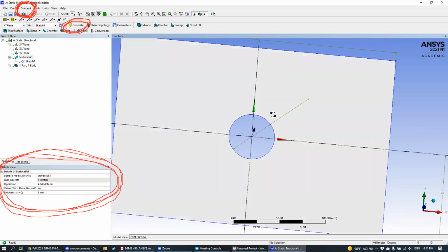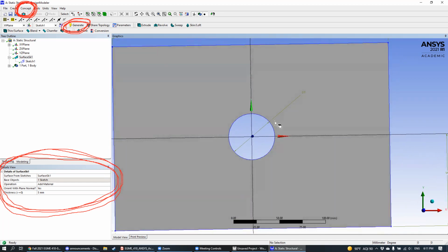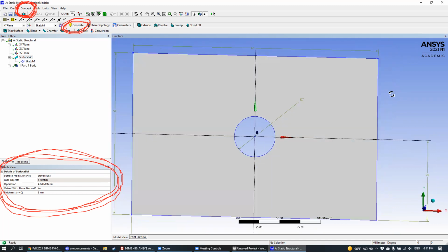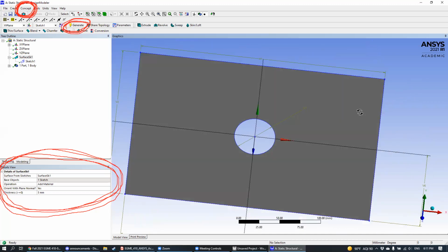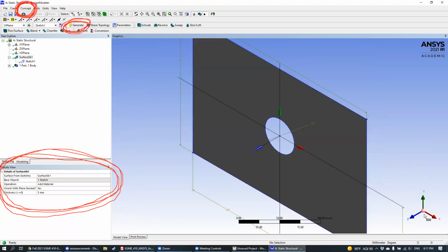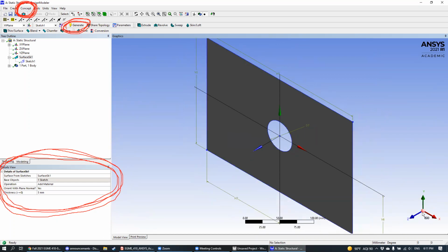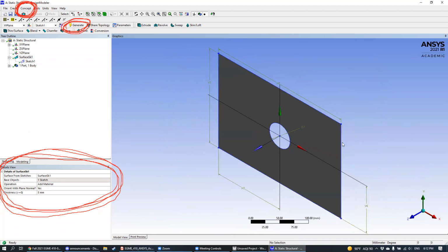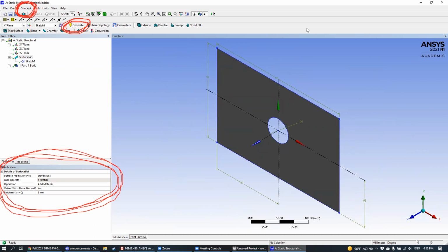All right. Any other questions on our geometry here before we close this up? I know somebody had asked earlier about the Control 7, the ISO view of stuff. If you click the little blue ball in the bottom right there, it automatically snaps it to ISO view. Oh, nice. I didn't even know that. That blue ball was there the whole time, and I never clicked it. I just happened to click on it by accident, and it threw me into ISO. So that's something new I learned about Ansys today too.